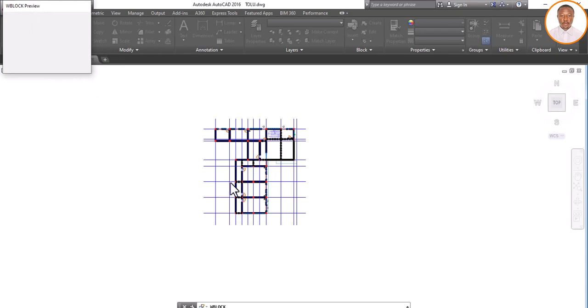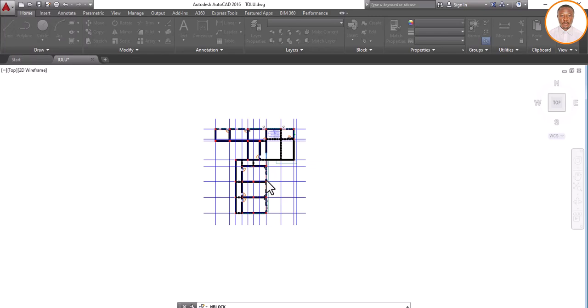You can see how we have taken our time to train you on how to position your column. Different structural engineers have different ideas of positioning columns. The most important thing is to make sure your column is well positioned in such a way that the span is not too much. As a beginner, it's advisable you stick to 6 meters column to column. If it's beyond that, you might not be able to handle it.